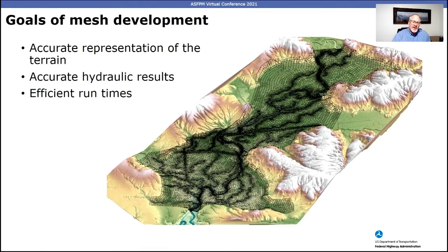So based on the models that I've reviewed to date, I tend to see folks that do SRH2D modeling select element sizes that are much smaller than needed, resulting in very large mesh sizes and long run times. And those using HEC-RAS 2D tend to use too large of elements, mainly because of the detailed representation of the terrain along each element face. But they often miss hydraulic controls, and they do not consider that there's only one water surface elevation computed for each element. And this is an important consideration in areas where hydraulic conditions are changing rapidly.